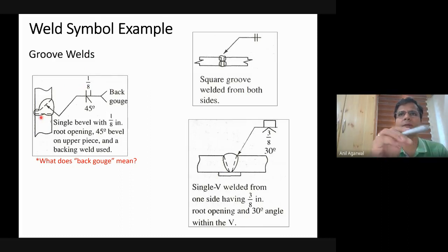When you do the tack welding, it will get disturbed. So you maintain whatever gap as close to this gap as you can. Then you go about doing the first weld from this side. From this side, the bevel edge. So you do the welding from this side.